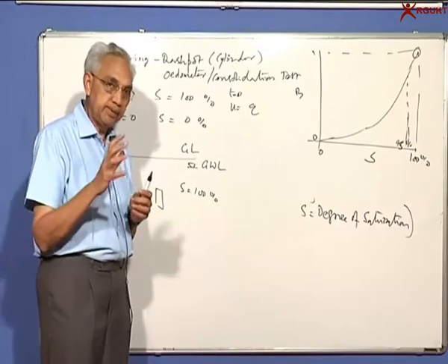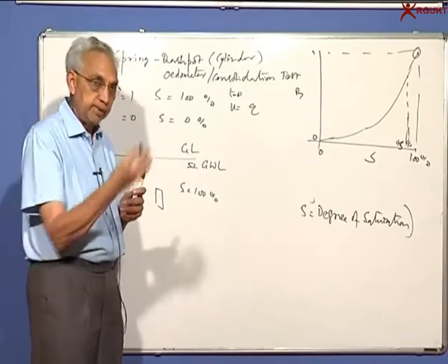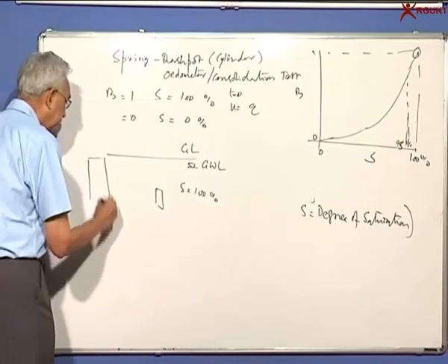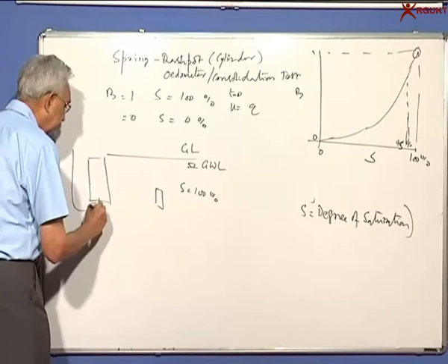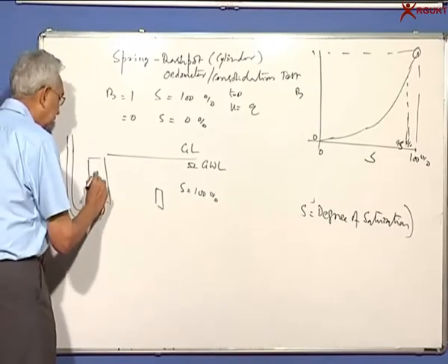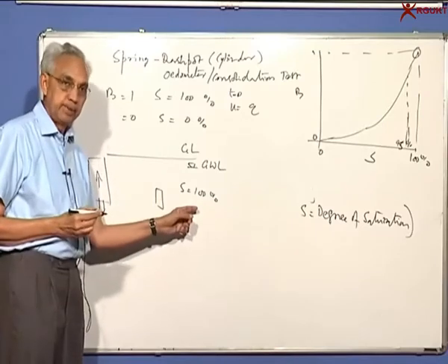Otherwise, you can saturate by continuous injection of water or by washing it through with a continuous flow of water. What we sometimes do is connect a reservoir like in a permeability test, and allow the water to flow through the sample to get 100%.